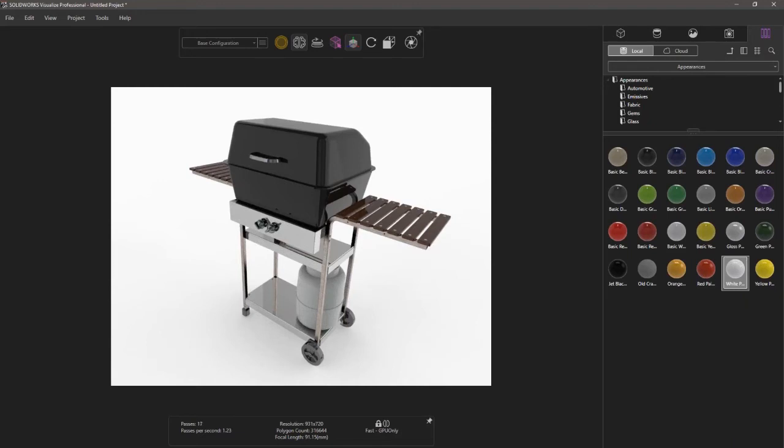To answer the question, someone had a question on the pivot snapping. Was it snapped to the correct place, or did I place it manually? I placed it manually. There is an option. If I'm using the pivot set to, say, the center of a bunch of components, you can move it to the center of an individual component. So there's an option there to use the pivot center of a component. Sometimes that works great. If it's like a bolt you have selected, you set the pivot center to the center of that bolt, boom. That's great because that's your axis of rotation. So there are options like that that you can use, but a lot of the time when I'm doing this stuff, it's getting it to look close enough so I don't have it completely dialed in.